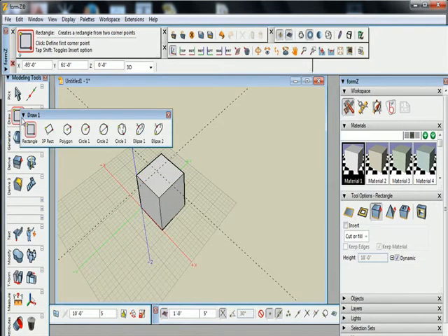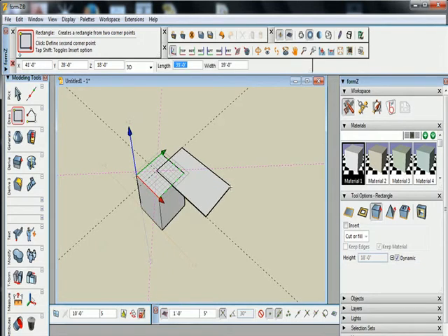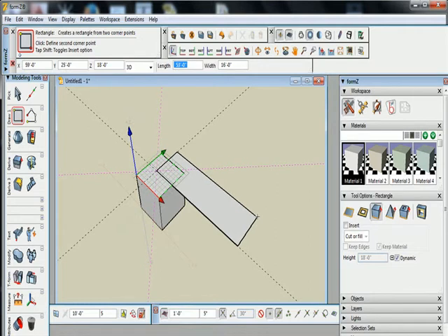So we're going to draw a rectangle again, and we'll go right to the intersection of guidelines that we drew. Okay, and that dimension is, what was it, 36 by 12. So what we want to do is type in the length, and if you ever get confused about which side is which, just look up here. The long side is supposed to be 36. You type in 36 feet, tab, and then it's asking for the width, which is 12 feet.